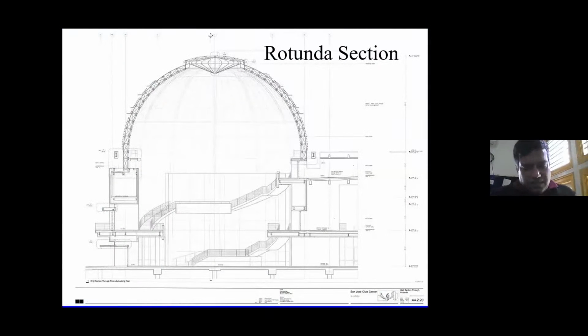Since it's 100 feet, and of course they had 2% as the criteria, even though we went with 2.5%, it's easier to explain the concept. The building is about 100 feet tall. In an earthquake, the top of the building would move by about 2.5 feet from its original position. And the criteria is nothing should happen to the glass. Of course, this whole building was clad using glass. This is the criteria from the code.